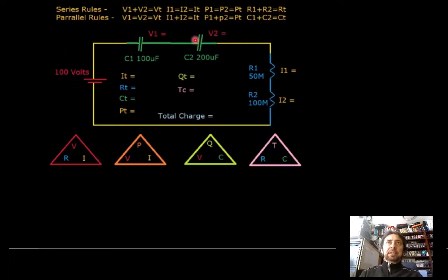Now, in this example, being a series circuit, we're going to find that the current is exactly the same no matter where we measure it. The current will always be the same, and that will be the total current value, which we calculate over here by dividing the voltage by the resistor. That also equates the same for power or wattage calculation. So the wattage calculation should be the same no matter where we measure it in the circuit.